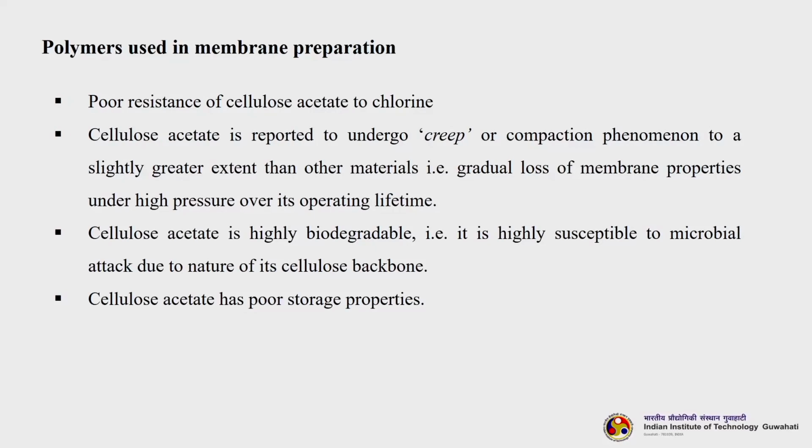And cellulose acetate is reported to undergo creep. Creep is a compaction phenomenon, and its compaction or creeping is slightly greater than other polymeric materials. So, that is the gradual loss of membrane properties under high pressure over its operating lifetime.